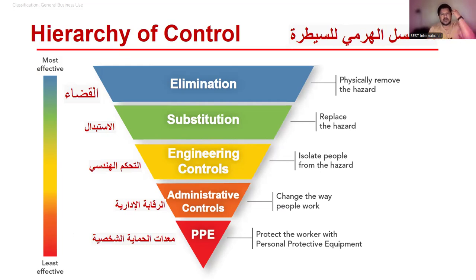Like in Saudi Aramco, if you're working in confined spaces, you can't stay there more than 2 hours. You have to come out after every 2 hours. And then if you are going to re-enter, make sure you do the gas testing, you follow the safety best practices, you follow the right set of rules and the permit and all that. You do the toolbox meeting again sometimes. And then the last, not the least, is the PPE, personal protective equipment.